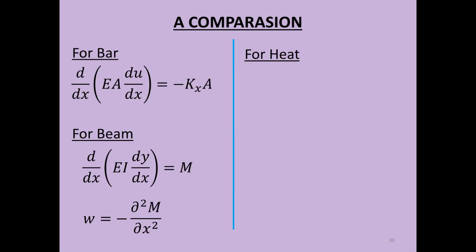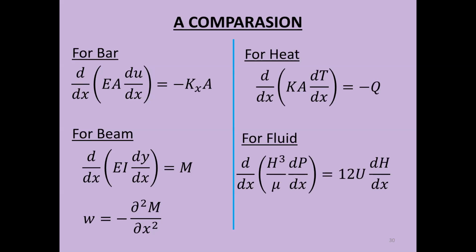And then we have a differential equation for heat, and at the end we have a differential equation for fluids. Now kindly notice that all these differential equations appear to be similar. They are similar in fact, which means that if you are able to make a program for one of the problems, assuming that you are able to make a finite difference program for a bar problem, then simply by making some substitutions you can solve the problem for other cases also.